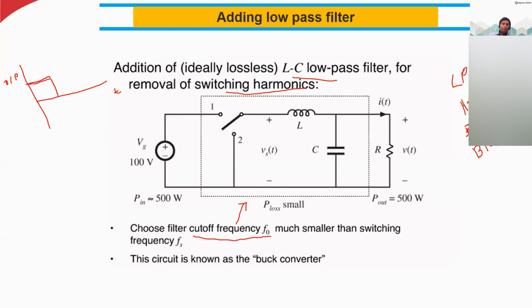So if you talk about this, you are passing only the low frequencies and blocking the high frequency components from the input signal. The high pass filter means what? It will only pass the high frequencies. So it will block all the low frequencies and pass only the high frequencies. This is the high pass filter. But of course, this is an ideal filter, in practice it will not be like this. It will be a curve. There will be a linear curve. So here it will not be a sharp rising. It will be a linear rising, right? So this is LPF, HPF.